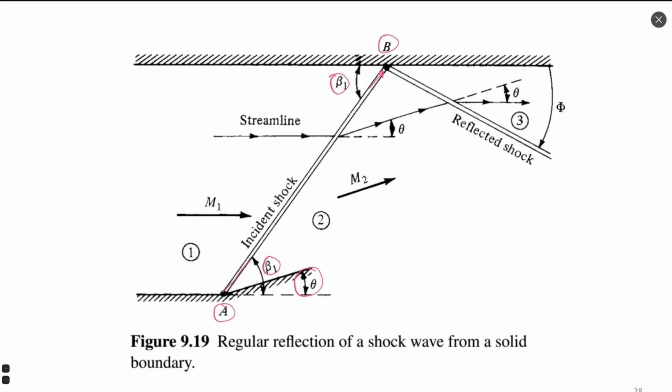Let's make such a calculation. What we need to understand here is one aspect that would allow us to calculate. We already know how to provide calculation at point A, right? So first, the oblique shock wave will not be a problem to calculate: Mach number, thermodynamic properties, and others. What happens with the reflected shock wave? What we need to consider, for example, is theta.